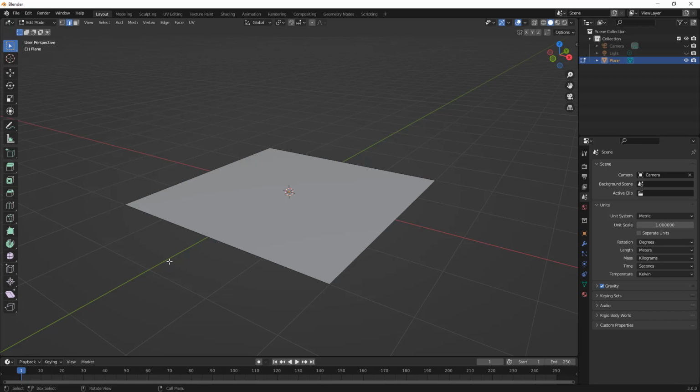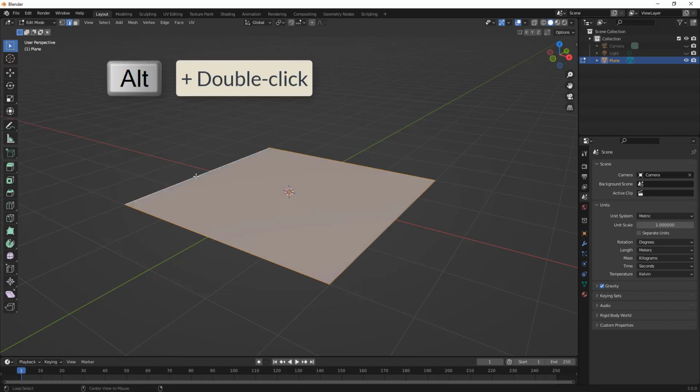And while I did say that I was going to avoid shortcut keys, I do think that making efficient selections on the screen is one of those areas where using the shortcut keys really makes sense. Now in Fusion 360 and plenty of other programs, what we end up doing is holding down Shift, double-clicking, holding down Control or Alt, and these are ways in which we can make multiple selections. And with that in mind, if we hold down Alt on the keyboard, now if you're on a Mac, you're going to be holding down Option, and we select an edge, nothing happens. But if we hold down Alt and double-click, you can see that it grabs the entire border.